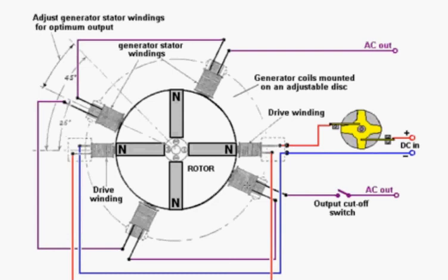So you're getting a very large push on the rotor, both from the pull of the magnets going to the cores and from the back EMF pushes of the rotor on its way as the magnet has just passed by.